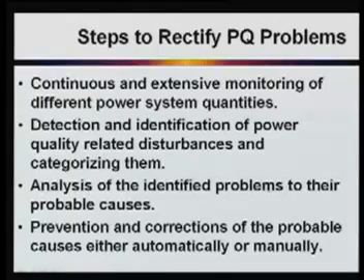By extensive monitoring, we can know which type of problem is occurring, whether it is a voltage sag, because voltage sags, swells, and transients are not continuous phenomena. They may occur once in a whole day, or once in a year or so. So continuous and extensive monitoring of the PQ, the power system quantities, is required.